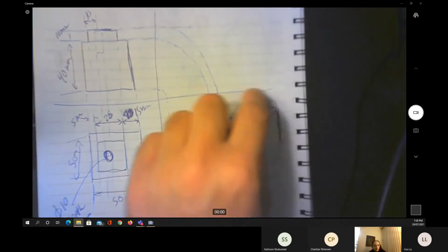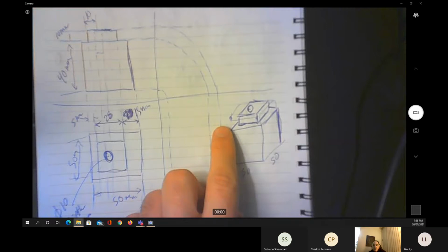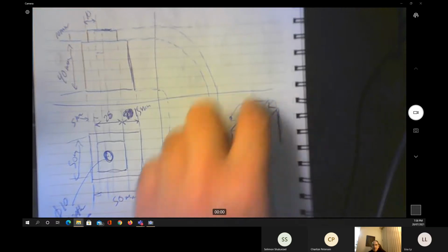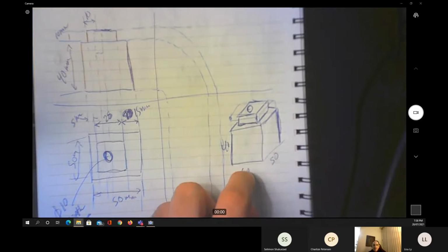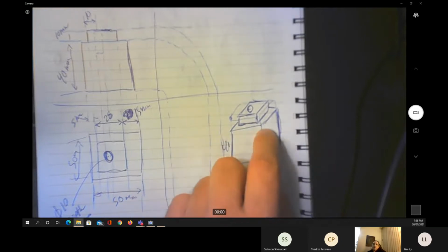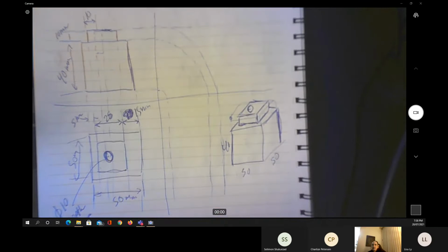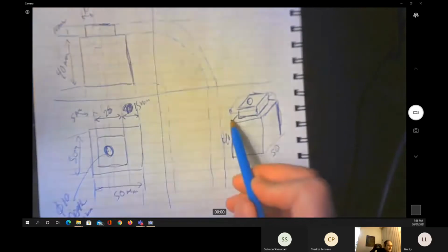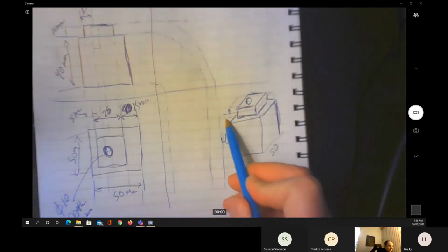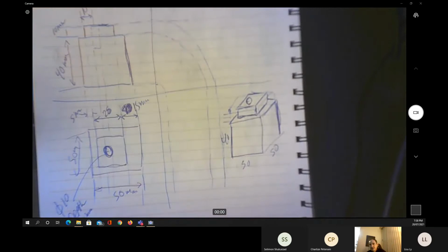So you write down the code of cleaning around this one once to the z of minus 4, then you copy paste the same thing to the z of minus 8, then copy paste the same thing to the minus 2. And then you're going to have a hole in the middle, and that's it. Okay, so that's what you need to cut around it. Do it in three steps, 4, 4, and 2, and drilling the hole, and that's it.